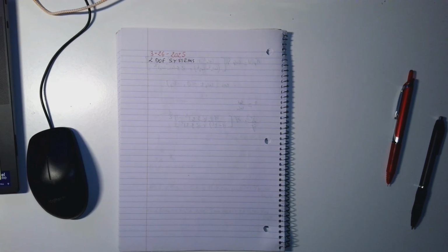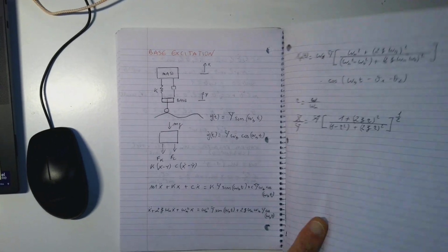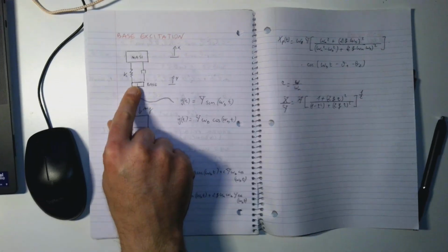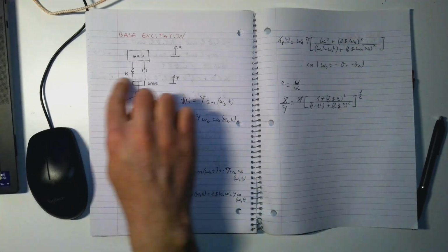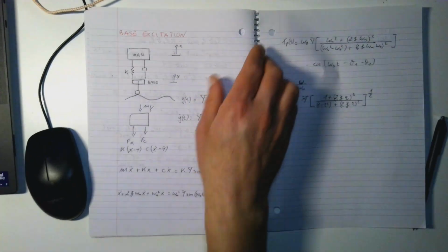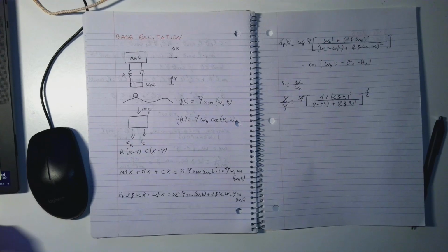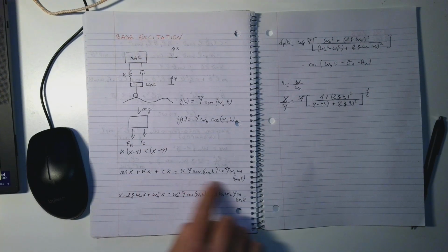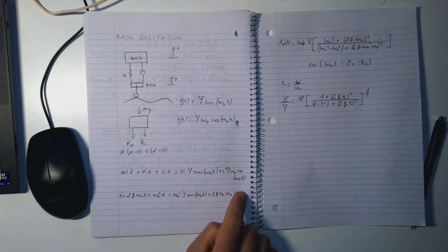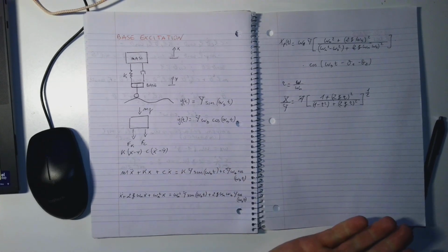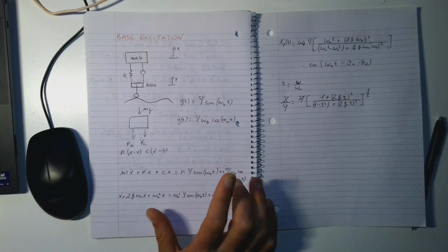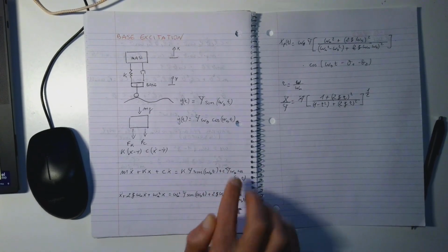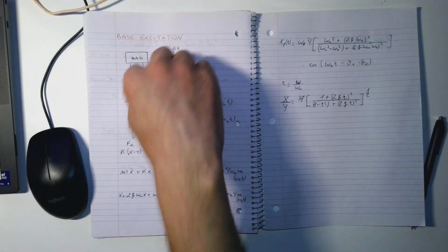Alright, so last time we talked a little bit about base excitation. We looked at what happened when we have one mass and one base, and there is some input from the base. In this case we saw that mathematically we have a little bit more to look at, because the equation of motion looks different, especially on the right hand side, because we have the input and then we have the velocity, so the effect of that comes from the effect of the dashpot, sorry.